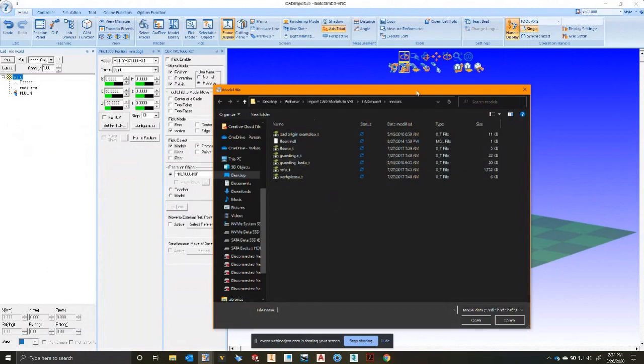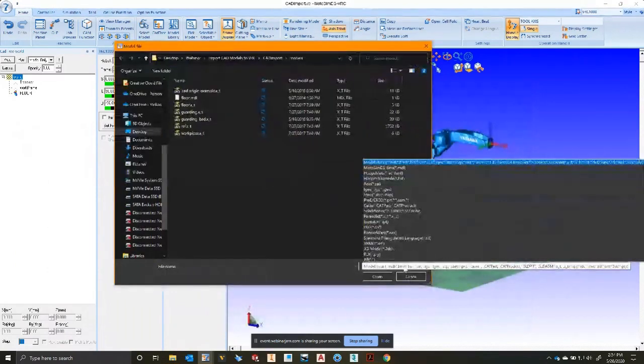Let's show you the formats that you can import. I'm not sure if you guys can read that clearly or not, but I'll read down through it. Hoops meta file, hoops stream file. These are the file types actually that are used by MotoSim. SAT file, that is a file type that is used in other CAD applications. That's also used in MotoSim. I stress to only use that though when you're using our CAM function. That's the file format required when you need to get a defined path, because it's actually using NURBS geometry.